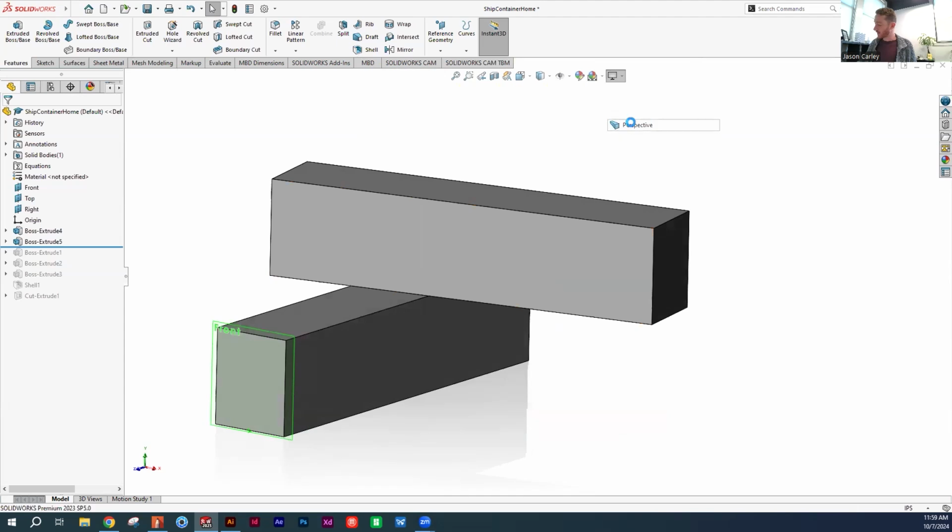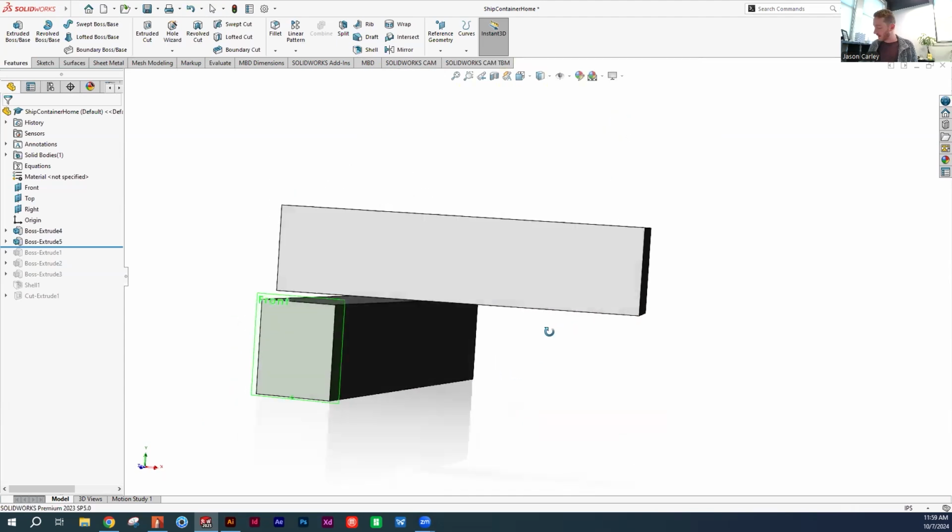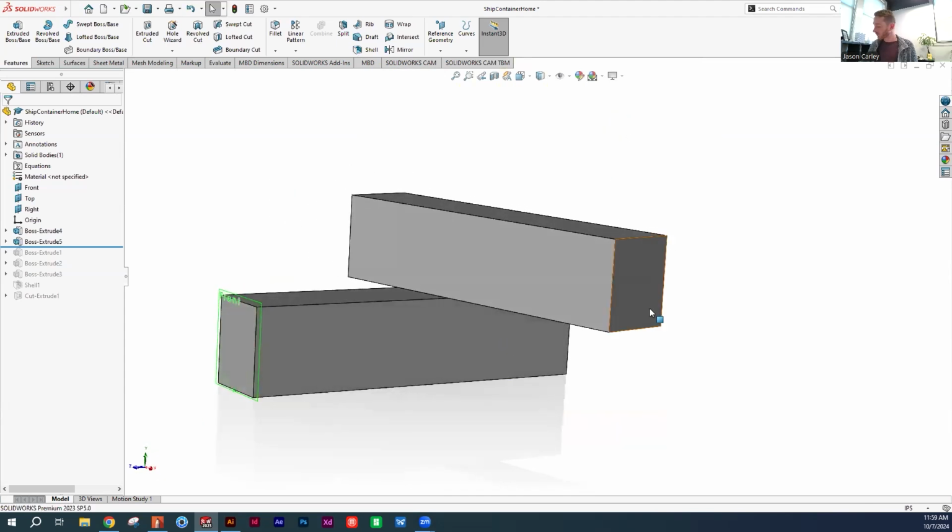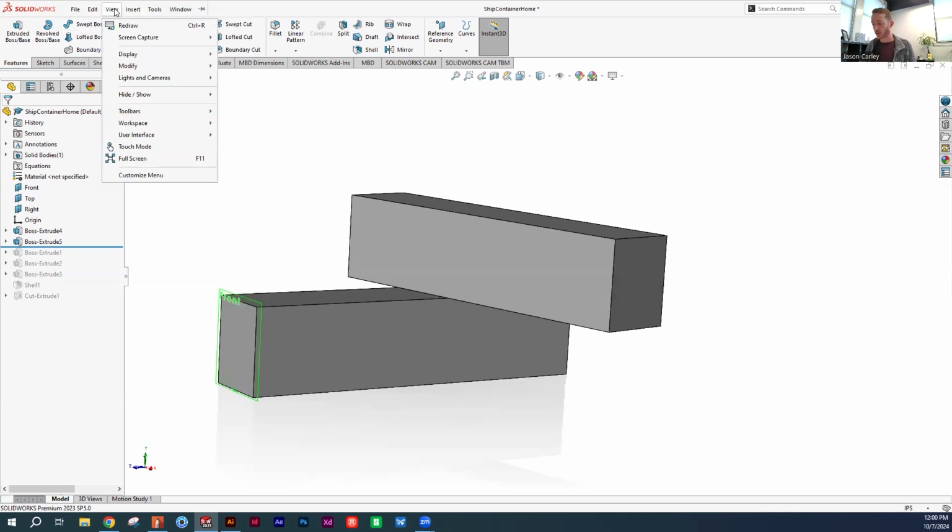If I go to my view settings, I can induce perspective. So it has some foreshortening. But SolidWorks isn't great about having multiple layers or an infinitely dynamic viewport system for controlling perspective. It really just has three stages. The first one is the most conservative. SolidWorks is built for typically working with small objects, so it has less foreshortening by default.